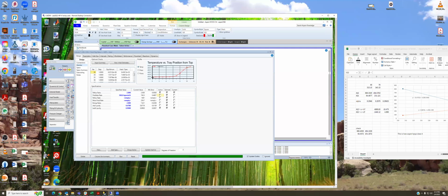The temperature profile looks reasonable. Our reflux ratio is 2. Our boil-up ratio is about 7.5. Our distillate purity is pretty close to the azeotropic composition that we estimated it to be. And of course, our bottom purity is at the specified purity since that's an active spec.